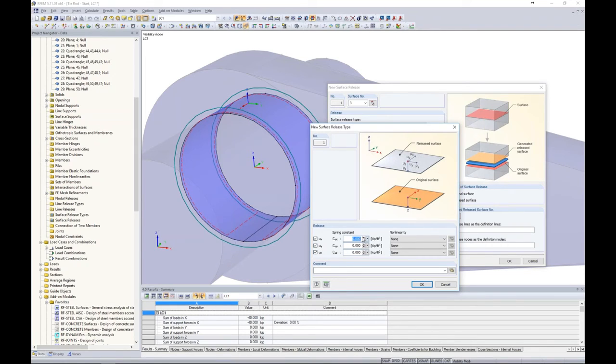So in the local X and local Y directions, I'm actually going to apply a small partial fixity. And that's because we're going to have some resistance of this bolt sliding left and right, front and back. So we'll do the same thing for the local y axis. Then we have our local z axis here. And again, sorry, I forgot to reiterate that these are lowercase x, y, and z, not to be confused with global X, Y, and Z indicated by a capital X, Y, and Z.